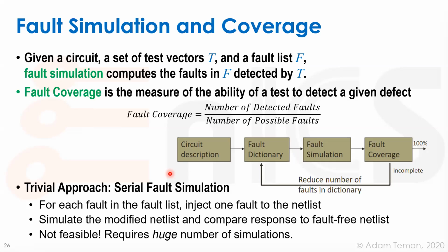What this is saying is, listen, I want to check the stuck at one fault on this and this net. How do I do it? I take all the different vectors until I find one, I push that vector through. I see it's supposed to have a 1 at the output. Now I change one by one the input pins until I get a 0 at the output. Aha, this one will check it. Let's add it to my test.